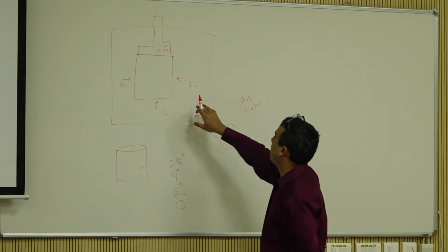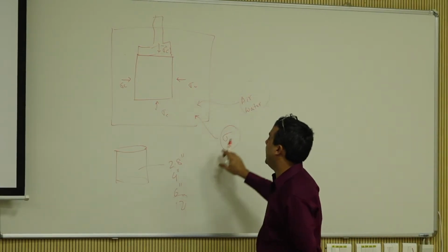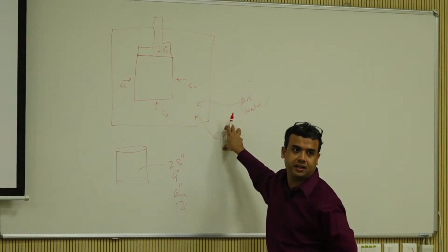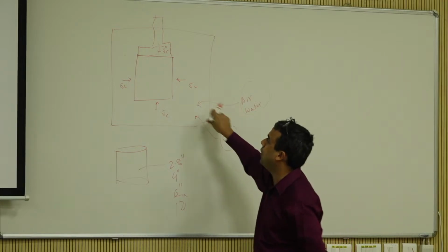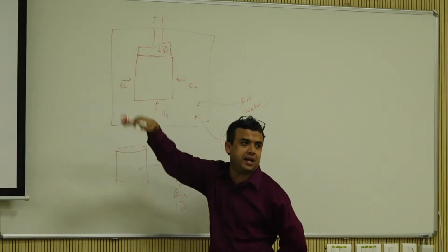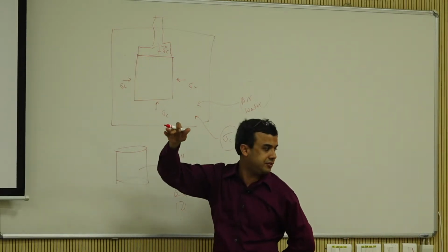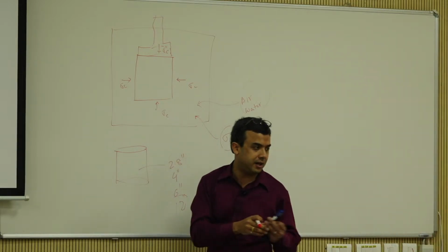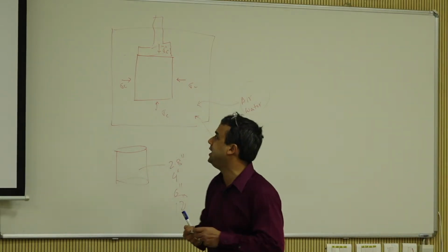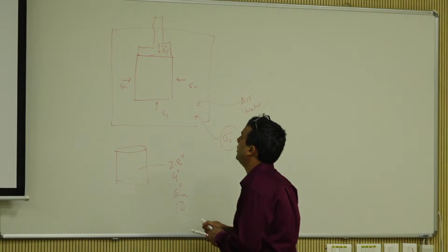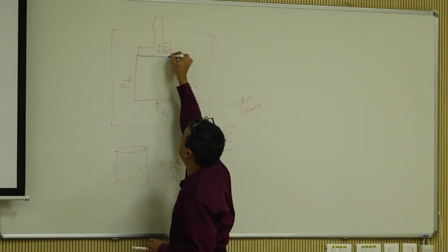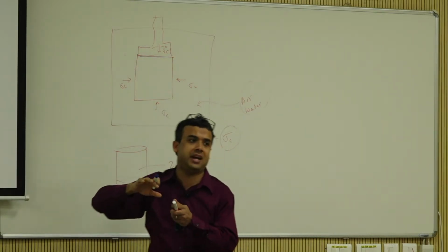So you're pressurizing the system, and you're applying what is known as confining pressure, and then you apply what is known as the mechanically induced deviator stress. We call it deviator because that is the deviation from its standard state.